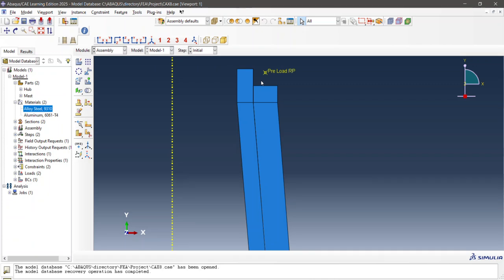So the mast nut itself doesn't get direct torque applied to it. It doesn't get the preload applied to it. It gives you the means to apply the preload though. The mast nut has 12 through holes drilled into it in its center all the way around that allow you to install a bolt.